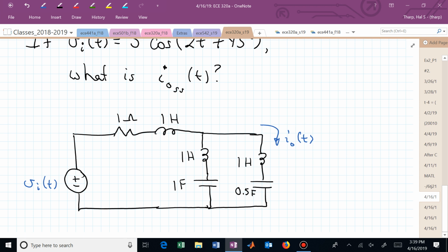Pardon? Where would you see something that is connected to this answer of fifth order? Where would you expect that number to exist or live relative to this circuit? So you're going to have a fifth order differential equation. That means that if you find a transfer function associated with this circuit, your denominator polynomial is going to be fifth order, generically, if you don't have any cancellations. Maybe we'll have some cancellations in this one, and we'll have to wait and see. Okay? But now how do we proceed?